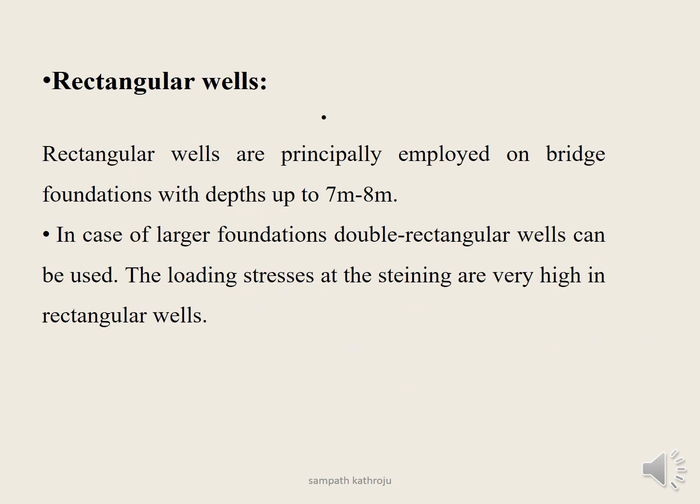Rectangular well. The depth is up to 7 meters to 8 meters. In case of larger foundations, this can be used. But the loading stresses at the steining are very high in rectangular wells.